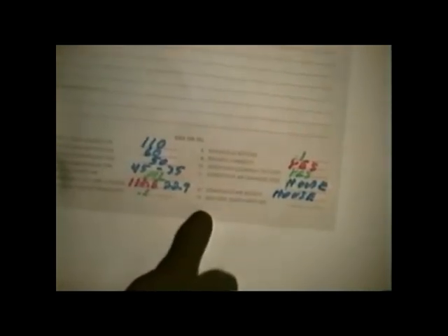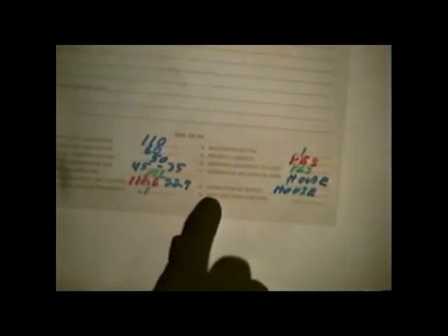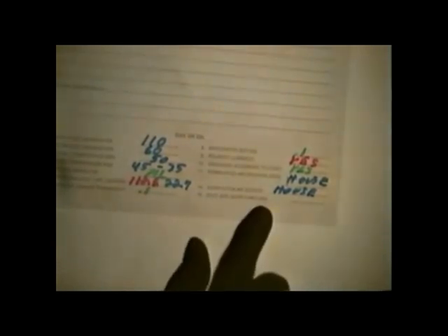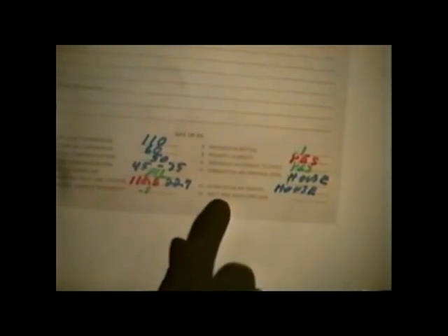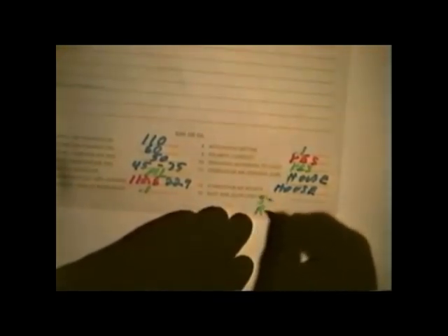Now, ladies and gentlemen, if you've been to my classes before, you know that my background is service, not an installer. And if you had a 75,000 BTU furnace, we need to be able to put the supply and the returns duct size. You need to be able to talk about them. You may have to talk about the extended plenum and what the size is and how many takeoffs there are. But Jeff, you would be better at this than me. What could I put down just on a form here for a return duct? 8 by 20. An 8 by what? 20. 20? All right, let's just put that down.